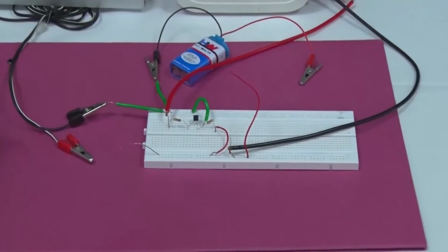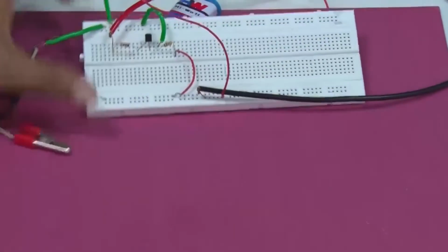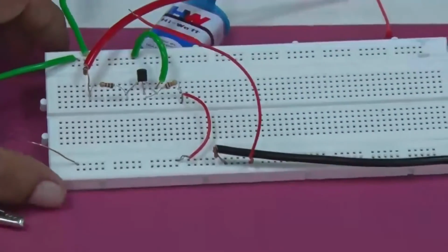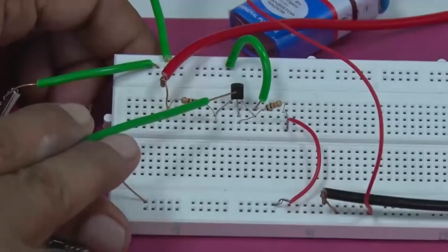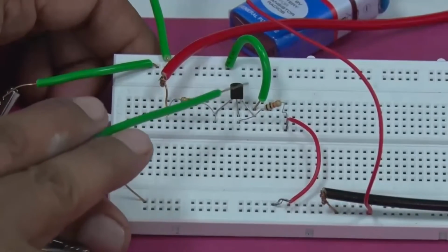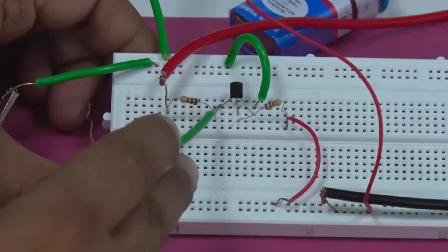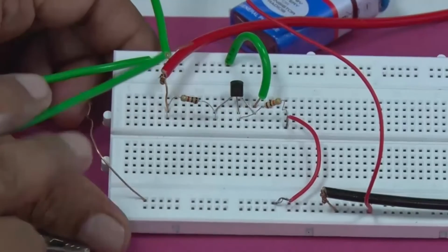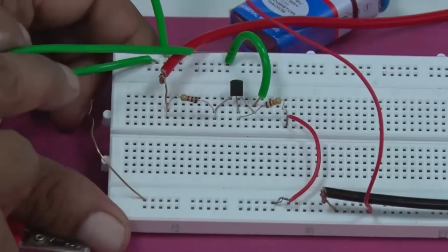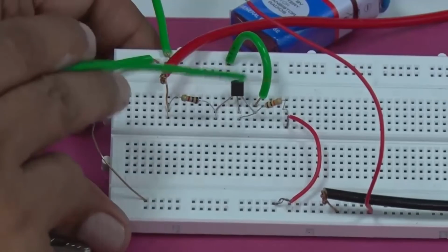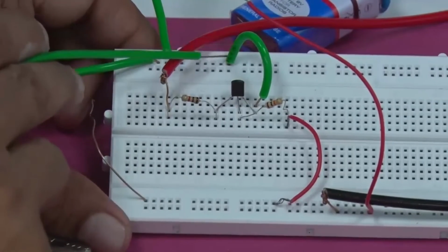So what you have here is, on that same breadboard, a similar circuit to what we had shown earlier. You have this transistor, this is the flat surface here, and this is the collector, this is base, and this is emitter, and this emitter is already connected to this ground line. This is my ground line. So emitter is grounded.